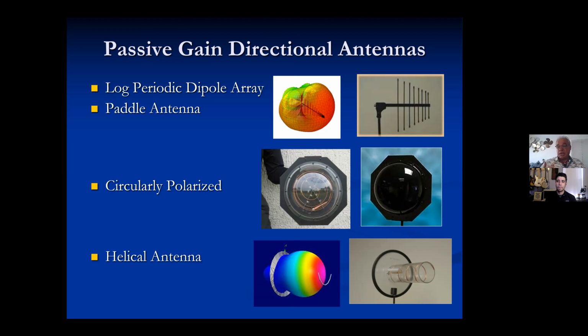But we can see light, and you can imagine light. So when you look at these antennas, picture a spotlight, okay? The helical is a very tight spotlight, but it's really bright. The CP is a softer spotlight with a wider gain, and it's not as bright. In other words, with the RF, there's not as much energy. You won't have the forward gain that you get out of a helical, but you'll have a wider coverage pattern.